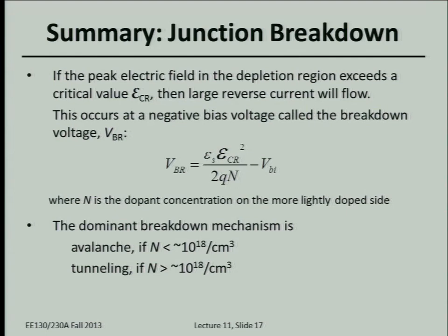More than 1 volt, right? Because the band gap is more than 1 volt. So it's more than 1 volt dropped across less than 10 nanometers. So that's more than a megavolt per centimeter. So it's a very high electric field.